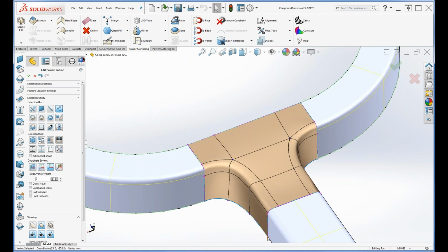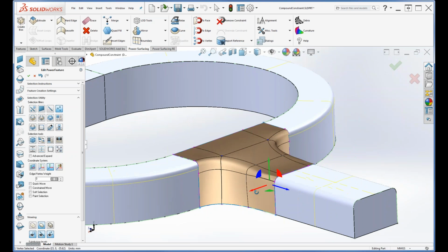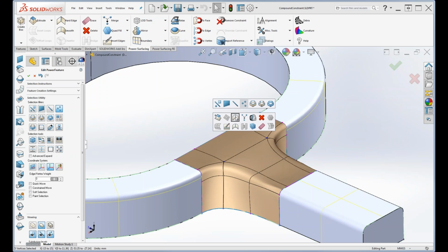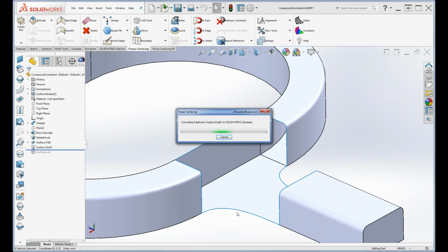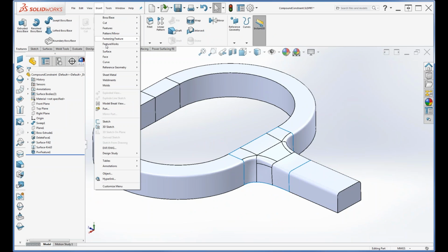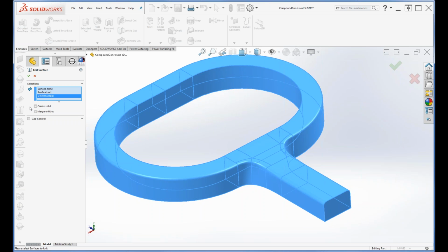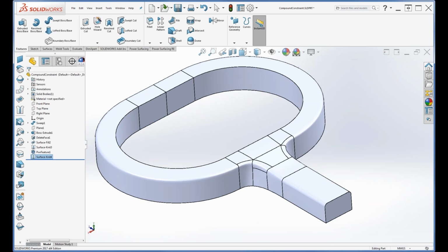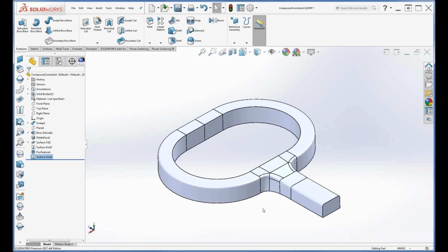So we would go through and select all of these corner vertices where tangency meets no tangency, and make them all 100% weighted. And that pops them in, and we can convert. And then, of course, you could do the whole knit thing, create solid, and there you go. So it's a kind of complex constraint, but it's very powerful in that you can work your sub-D to connect between a lot of different sorts of things.